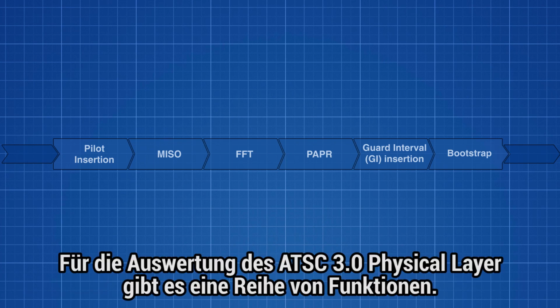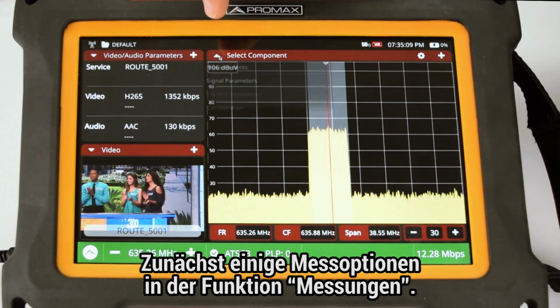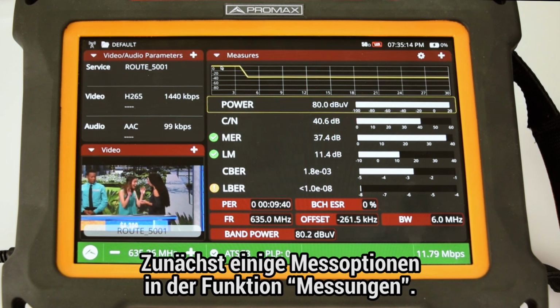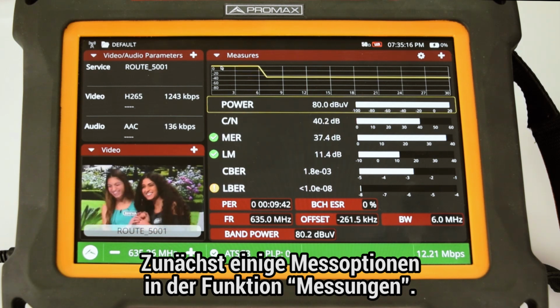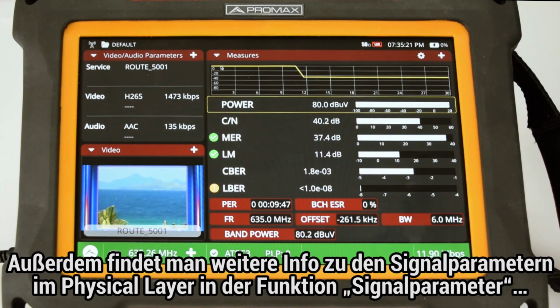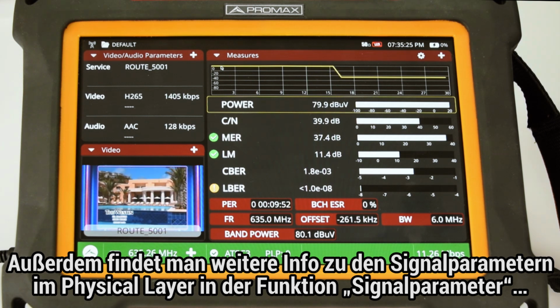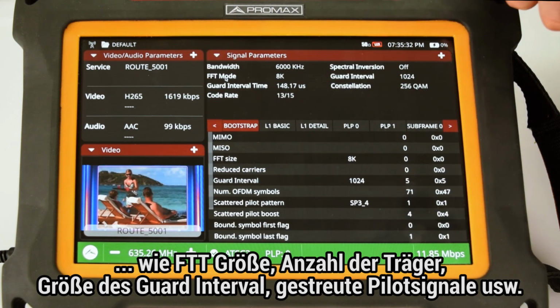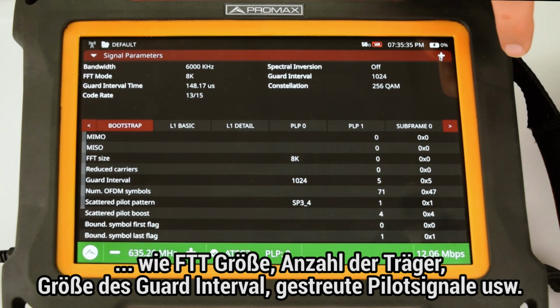We find a whole set of tools aimed at analysis of the ATSC 3.0 signal physical layer. The first of them are the measurements of power level, carrier to noise, MER, link margin, CBR and LBR of the carrier tuned, which we can find in the tool Measurements. Secondly, we can find more information on the signal parameters related to the physical layer in the Signal Parameters tool, such as the FFT size or number of carriers, guard interval size, scattered pilot pattern, and so on.